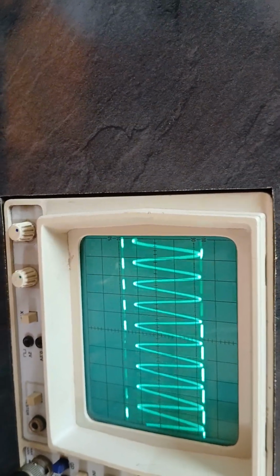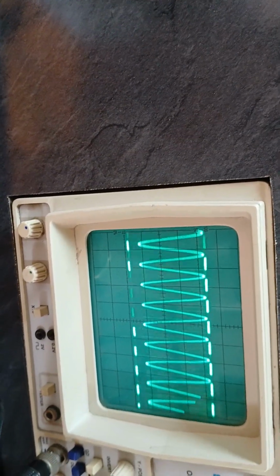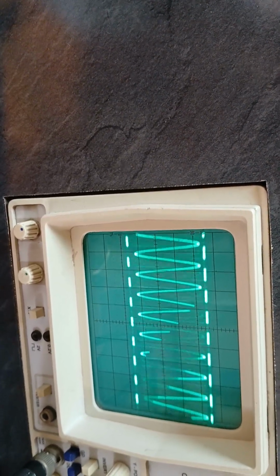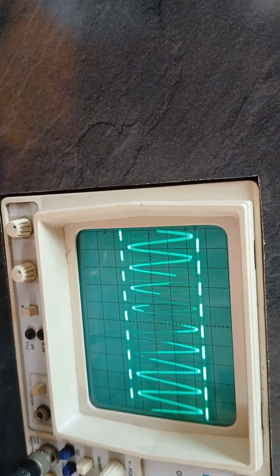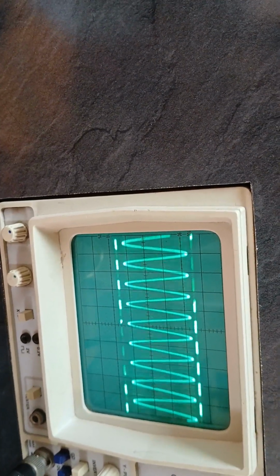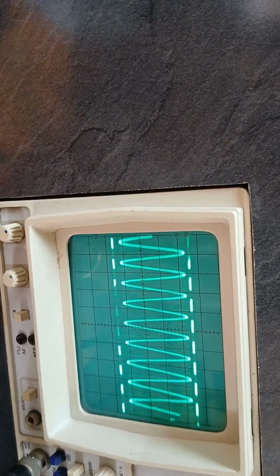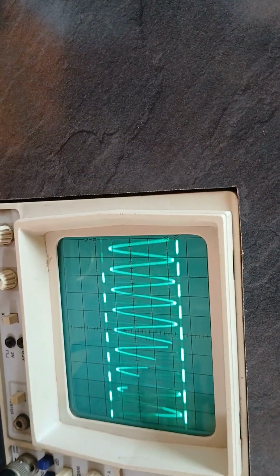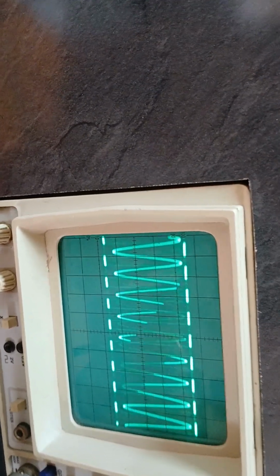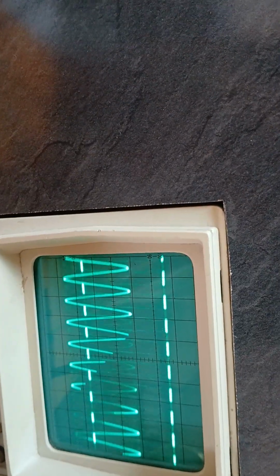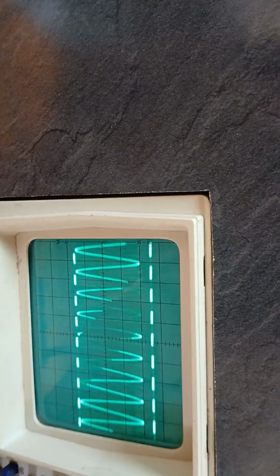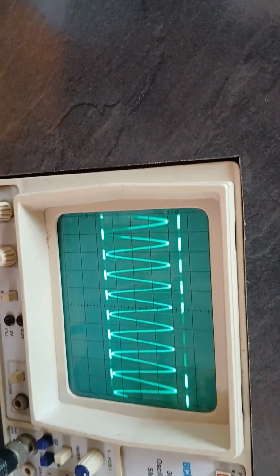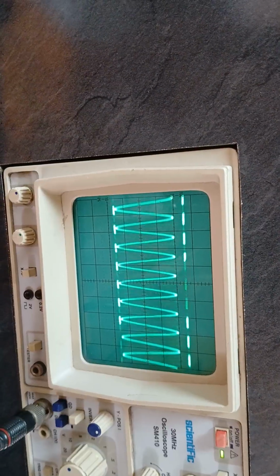So the Schmitt trigger is a comparator circuit which compares the reference voltage with the input sine wave. Whenever the sine wave input exceeds the reference voltage, based on the virtual ground property, it generates plus V saturation, the positive part of the square wave, and when it is below that value, it generates the negative pulse. So you can see a perfect square wave. For this reason, we can also call the Schmitt trigger a sine to square wave generator. That is a very important comparator application of the op-amp. Thank you.